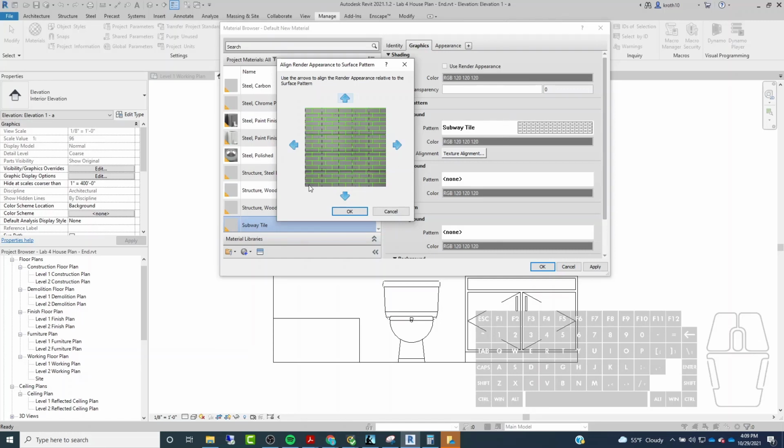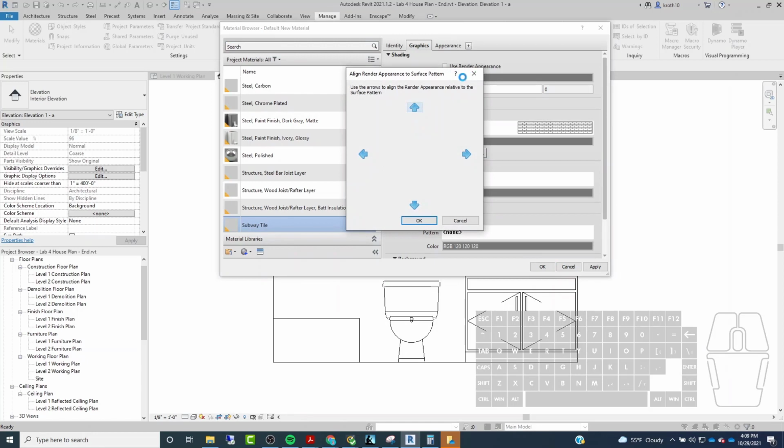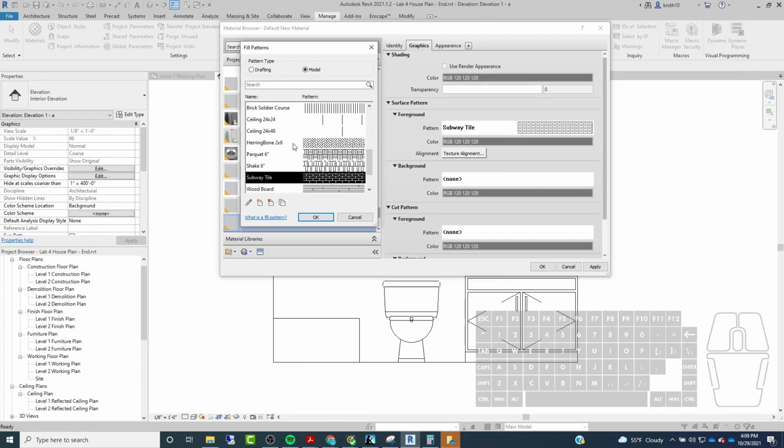We indicated that we had 5 across. So 1, 2, 3, 4. So we have 6. So that means we need to get rid of a whole tile. So let me make this a little bit bigger. This is definitely easier to do with tile patterns that are square, because you can just set those to be like 4-inch tile, for example.